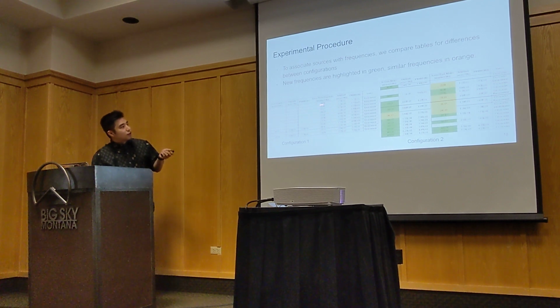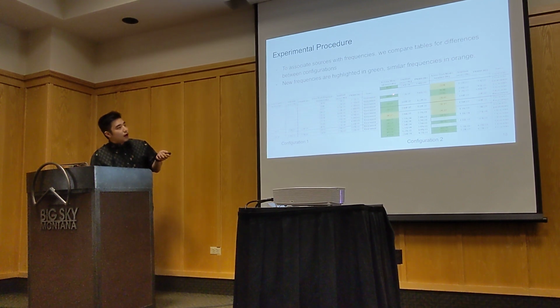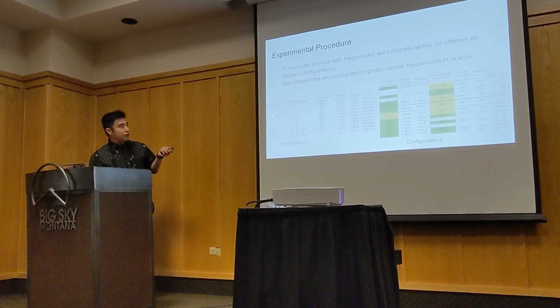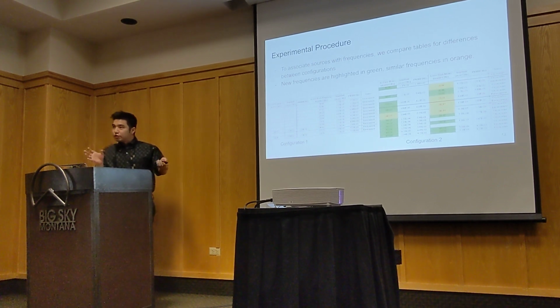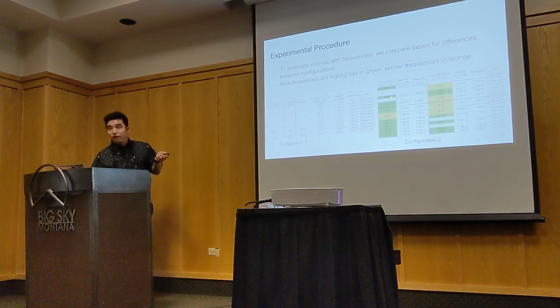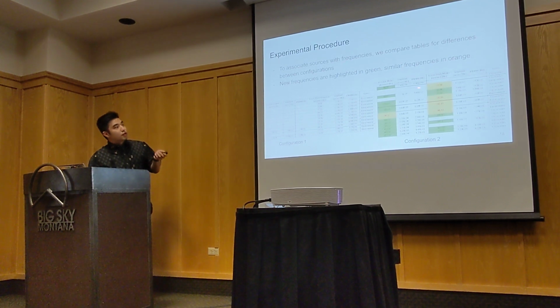And so you can see that, for example, in the in-track direction, configuration 2 had a peak at 60 hertz, which is not present in configuration 1, where the cryocooler was not active. Because the only difference between those two configurations was the vibrating cryocooler, it must have been the cryocooler.